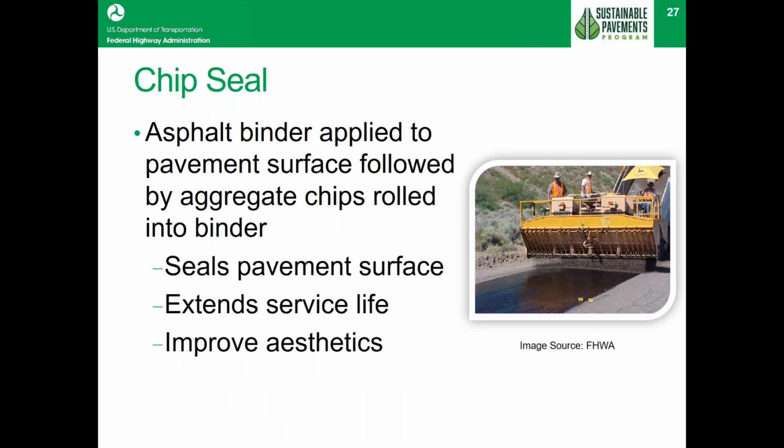The next treatment is one I think everyone has seen. These are the typical chip seals that are out there. People either like them or they don't like them, but they do have some pros and cons in using them. Typically, you'll find that chip seals are low cost. They do provide a very effective seal on the roadway. They cover many, many problems in the pavements, a lot of distresses and that kind of thing. Sometimes on very low volume roads, it tends to be the only surface that's put down. In some locations, they have done that very successfully.